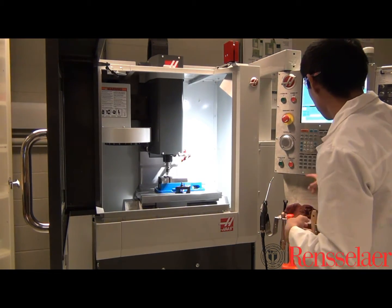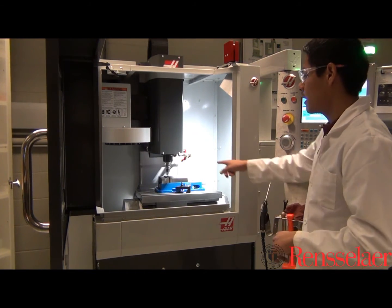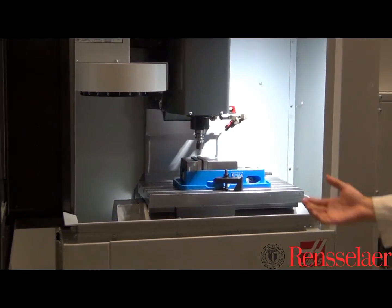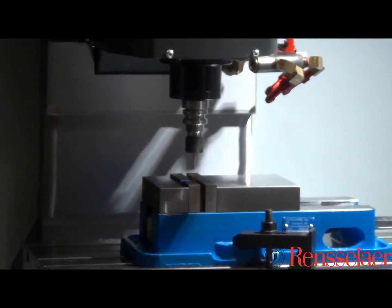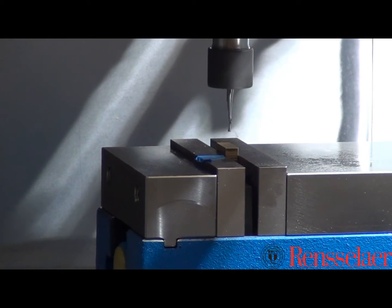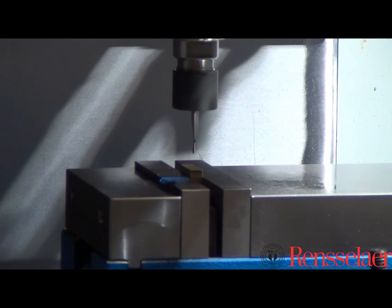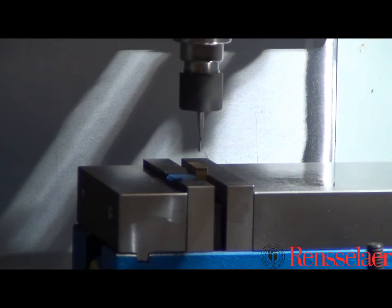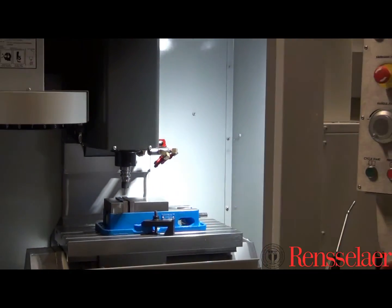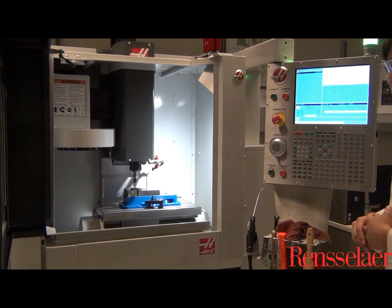So continuing, once we press the clockwise button, as you can see, the spindle starts spinning. As I mentioned before, the spindle starts spinning at about 700 RPM. Again, this is just a safety feature so that we don't cut ourselves or anything of that sort. So now, in order for me to have better control of the spindle, I'm going to change the step size of the Handle Jog wheel to 0.001. So we go Handle Jog, press the 0.001 button.